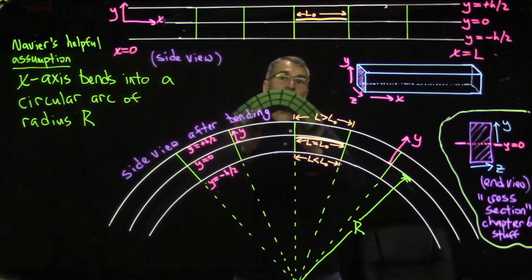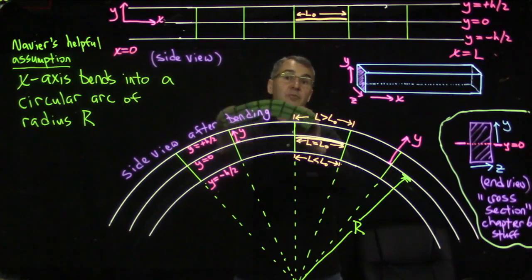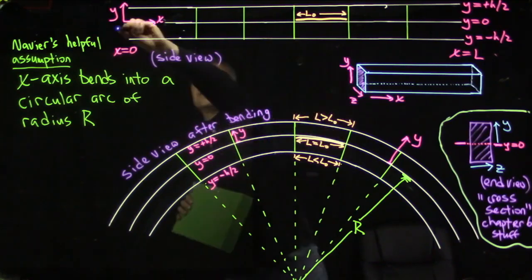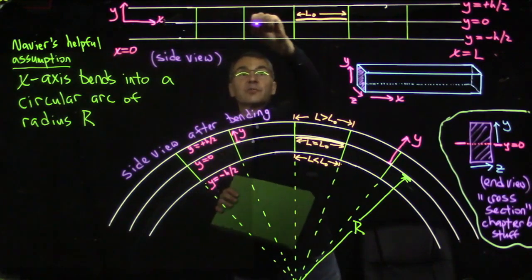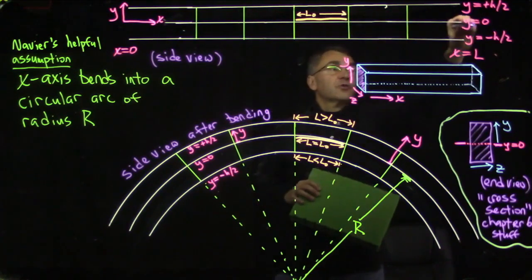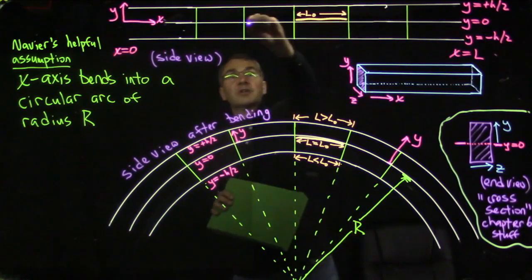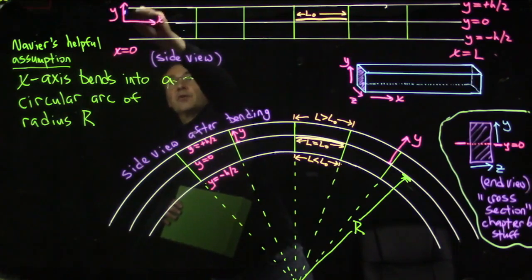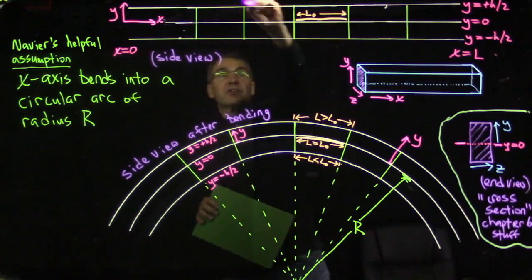So when a beam bends into a frowning shape like this, the material on top is stretched, it's in tension. The material on the bottom is compressed, it's in compression. And somewhere along the middle, there is a neutral surface whose length does not change. In this diagram, we've drawn the x-axis to be along the neutral surface, and this neutral surface is defined by the variable y equals 0. So we're saying y equals 0 is the neutral surface. Y is going upward. Y is also the direction in which gravity acts.